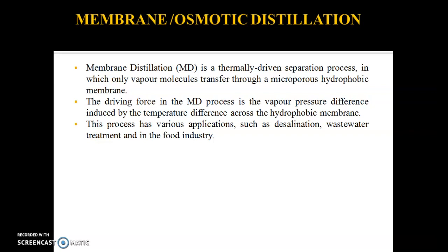Membrane distillation is a thermally driven separation process in which only vapor molecules transfer through a microporous hydrophobic membrane, meaning a non-wettable membrane. The driving force in membrane distillation is the vapor pressure difference induced by the temperature difference across the hydrophobic membrane. This process has various applications like desalination, wastewater treatment, and also the food industry.